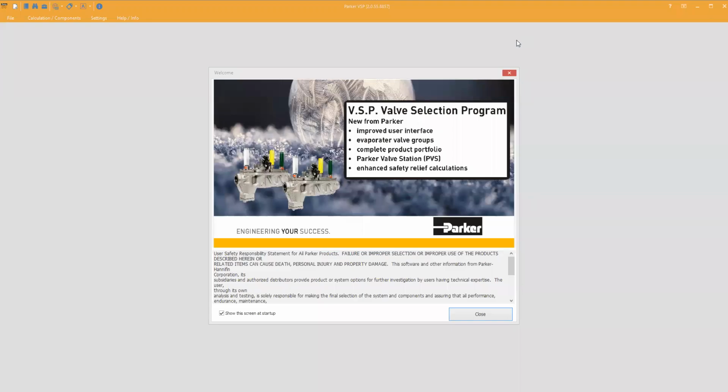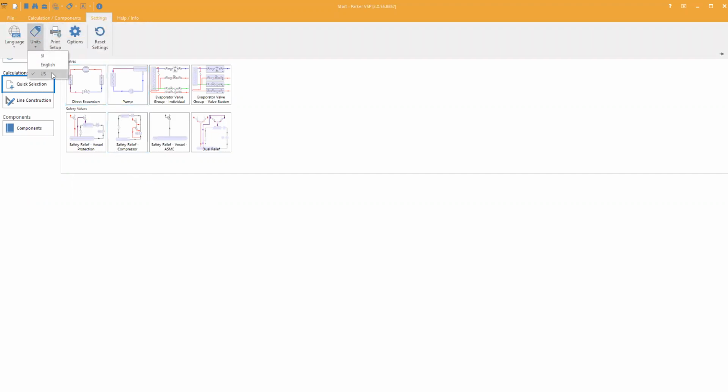In this video, I'm going to be walking you through how to select an ASME rated safety relief valve using Parker's valve selection program. Before we begin, you want to make sure that you have selected the correct units. In order to do so, you want to click on Settings, Units, and then make your selection.